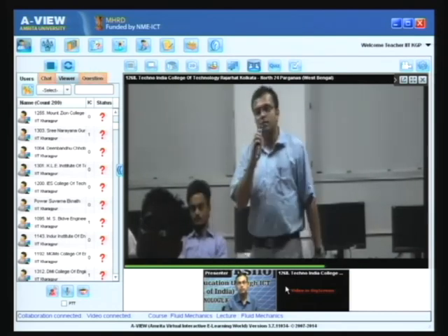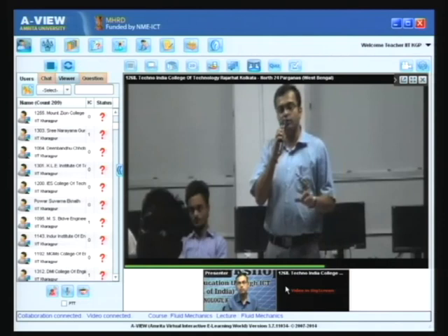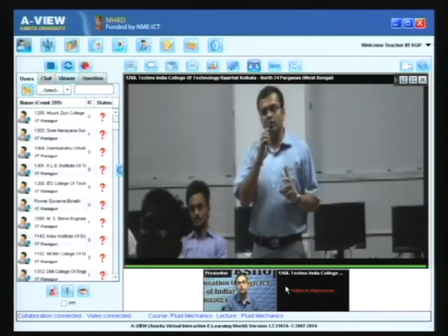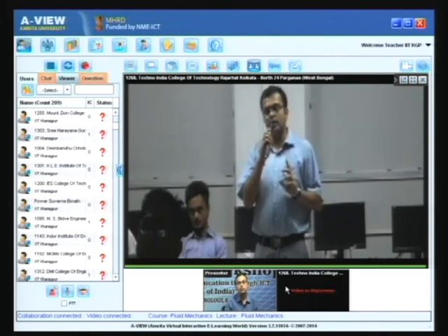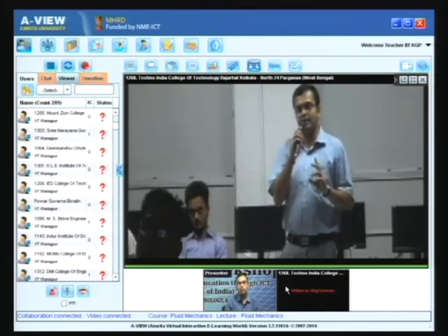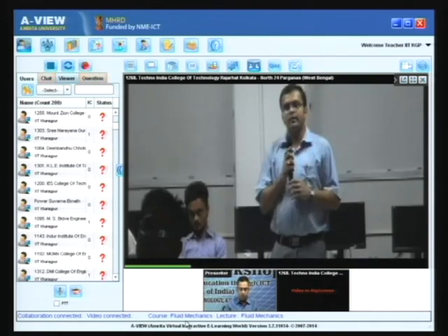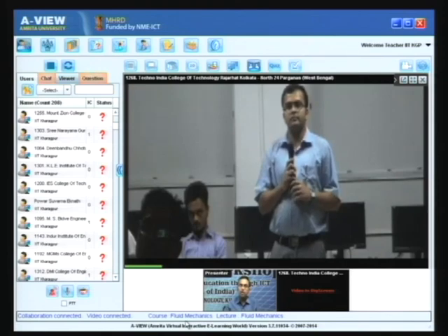Sir, in the rheological curve, you have stated two non-Newtonian fluids. One is called dilatant and another is called pseudoplastic. In both cases we have seen it is not obeying Newton's law. Can you elaborate these two fluids a bit, the major differences and their applications? Let me tell you, let us consider a polymeric solution, an entangled polymer solution, and then if you apply shear stress, the polymer chains will be broken.